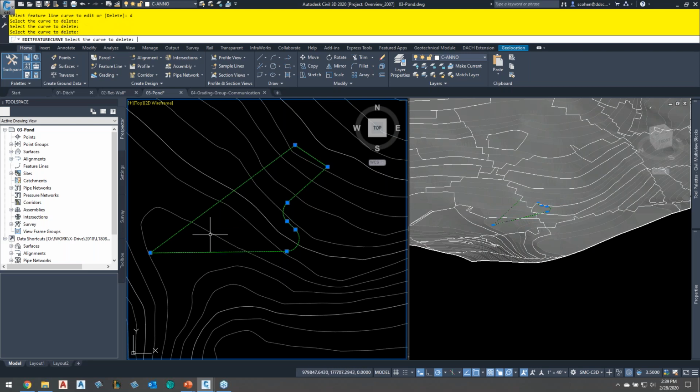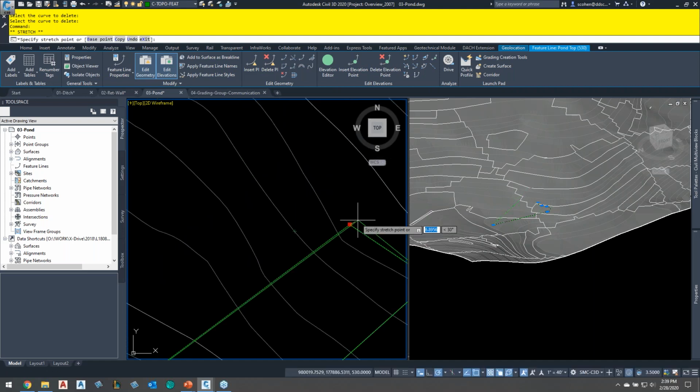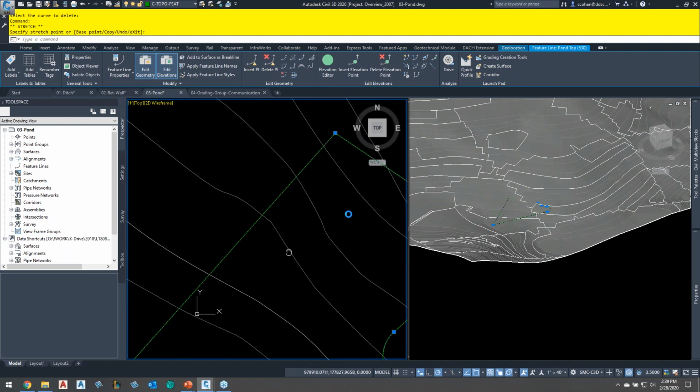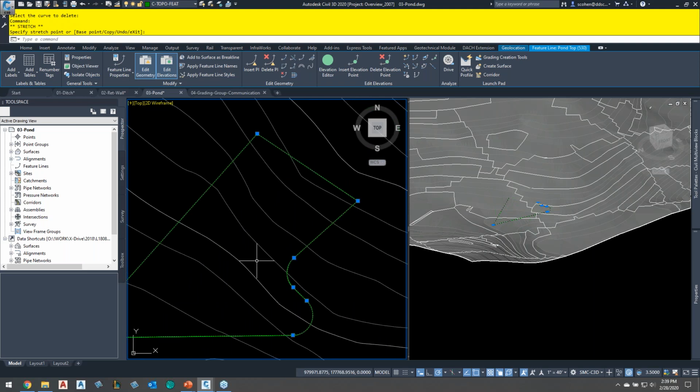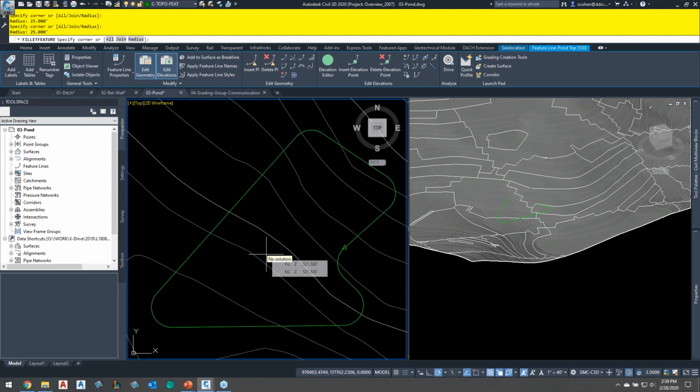Now I can go in here and I can resize the pond. You know, it does honor AutoCAD tracking. So if I have O tracking turned on with extension, I can just make that bigger that way. However, I need to do this here, etc. And then all I do is simply go back to the fillet command here, and I'll just refillet them. So you don't have to go through and explode it and get rid of it. There are many ways to do that in here.